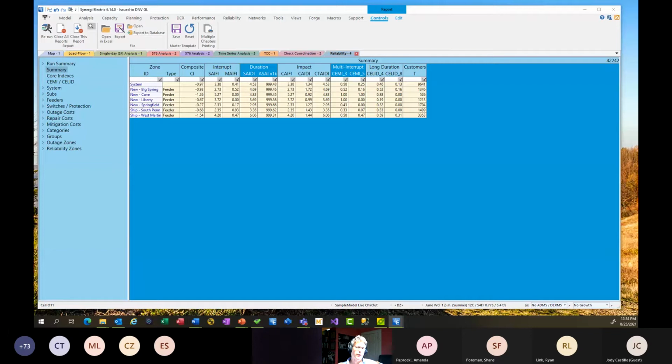Now if we run load allocation, and let's say load allocation wants to have a load on that section of, pick a number here, 50 kW. And we're allocating at a time where we have 50% on the profile. It's going to take that 50 kW and divide it by the 50%, and it's going to give us 100 kW, which is going to go into the edit box.